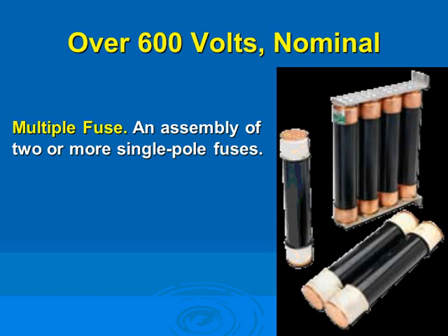How often is your system fully loaded? If you have a short circuit condition here, and this is open, and these continue to operate, what's going to happen to the short circuit? You're still pumping current into it, so almost all of them have to open to clear the fault here.